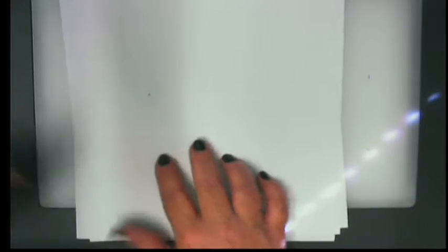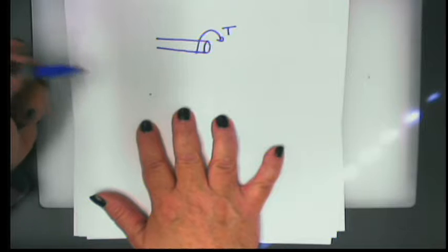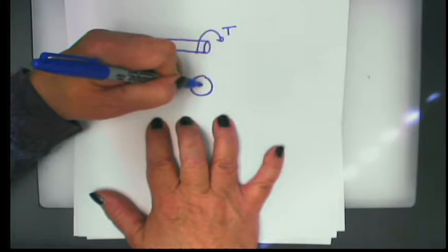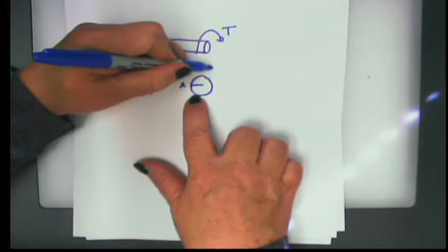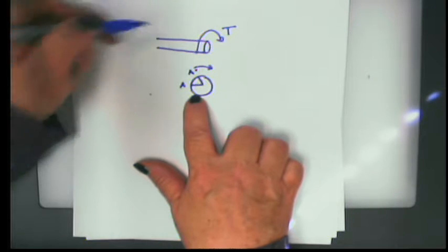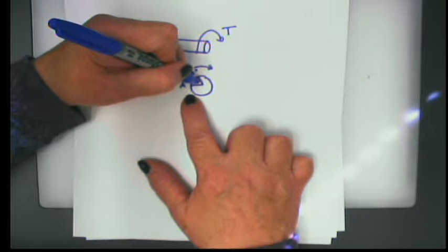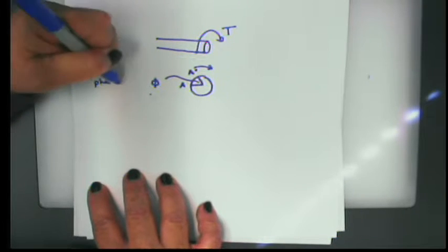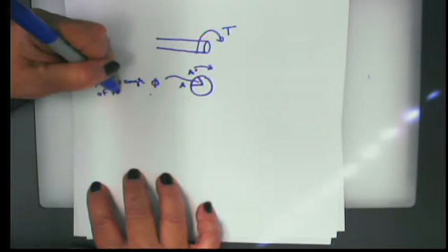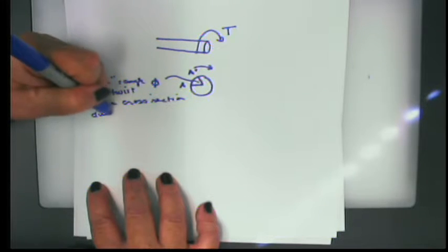So once again, we have a circular shaft stuck in the wall, subjected to a torque, and it twists. If we look at that initial cross section, if we look at a radius that used to go from 0 to point A, when we subject it to the torque, point A moves up some distance. This is greatly exaggerated under most circumstances to some point A prime, and we subtend an arc, AA prime, by the angle, which we call the angle of twist, which is designated by the Greek letter phi. Okay? So phi is the angle of twist on a cross section due to a torque.